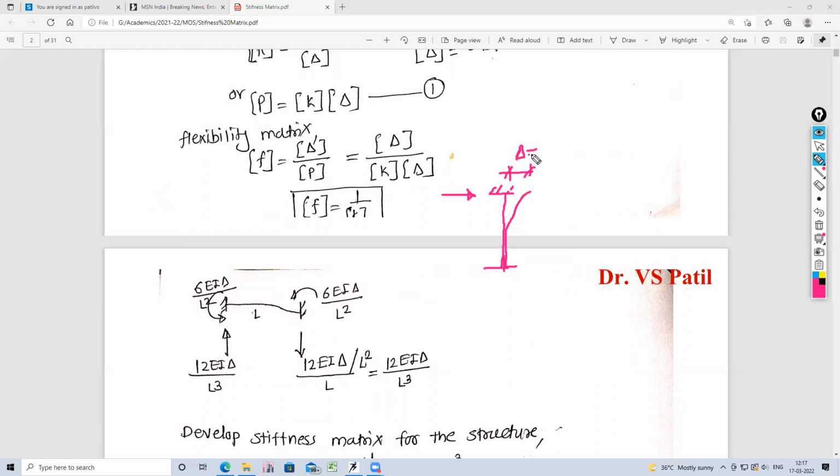So in the case of stiffness, to produce this value equal to 1, that is lateral stiffness equal to 1, how much P force is required is the stiffness. Whenever we apply some force here, this end of the column remains at the same location, while this end of the column will move by an amount equal to delta. So this becomes a level difference between the two ends, between the two supports.